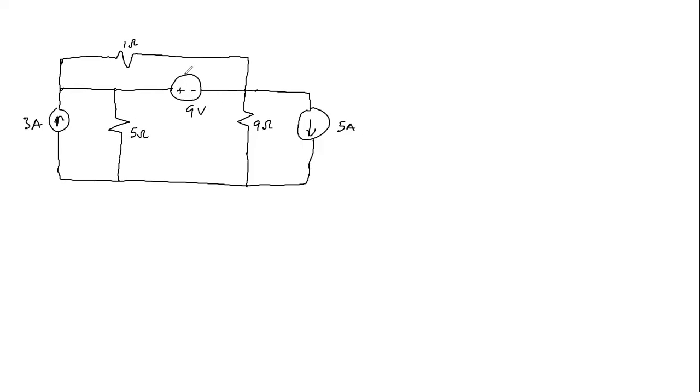Well, in resolving any circuit using nodal analysis, we want to identify the nodes first. So that's the first thing to do. Some circuit structures may be confusing sometimes, but if you look at this point carefully, you will see that these 3 elements, the 1 ohm resistor, the 3 amp current, and the 5 ohm resistor, are all connected on the same node. So in other words, this is a single node.